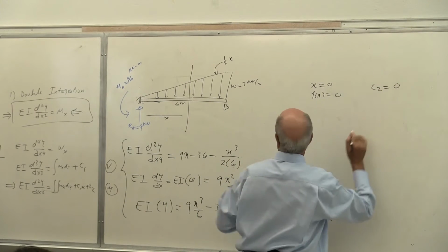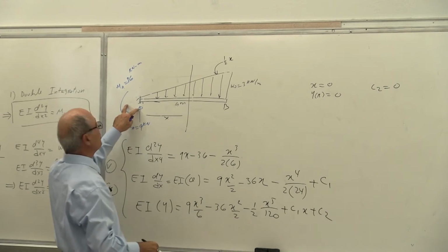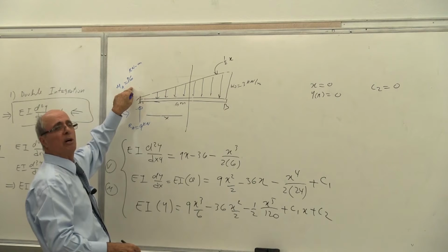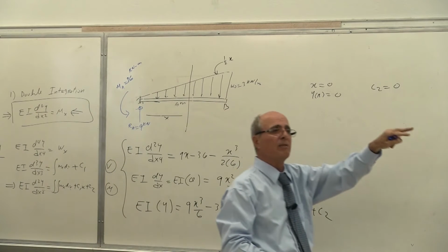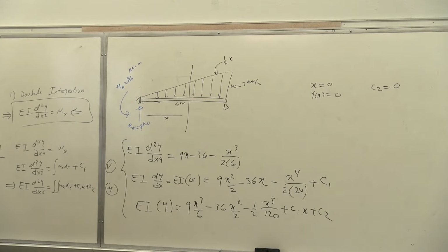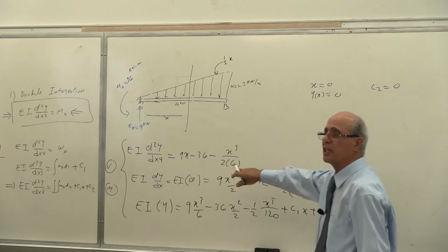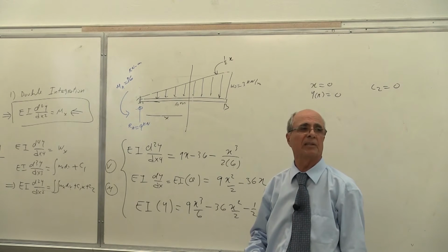Anytime you have a fixed support at the beginning, actually it is to your advantage, because you have two boundary conditions here at x equal to 0. You don't want the boundary condition at the end; that's mathematically more complex. Everybody appreciate that? Yes or no? I have seen students turn this around because they are afraid of their moment diagram. Remember, you write the moment equation, but here this becomes very simple. Is that correct or not?